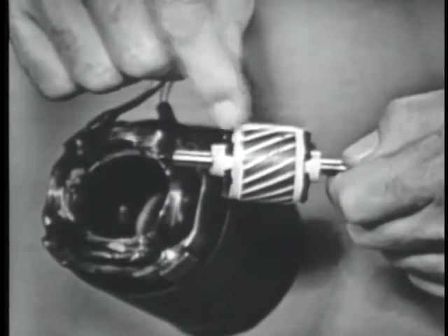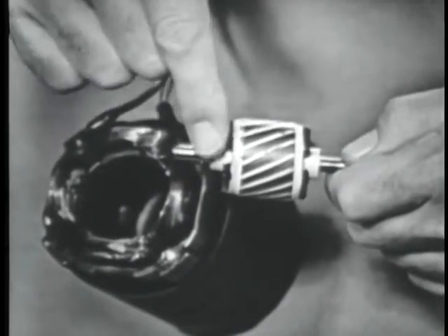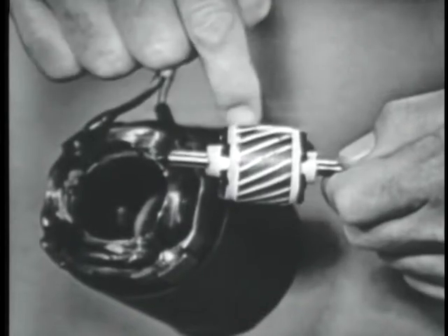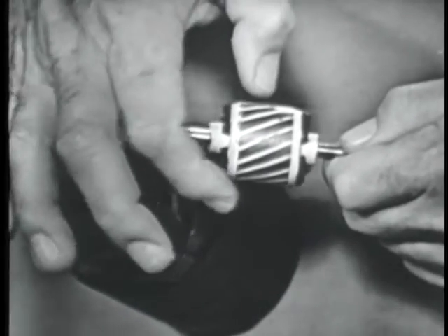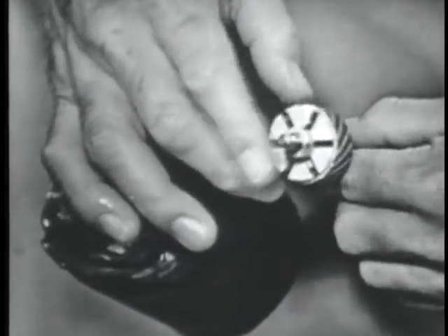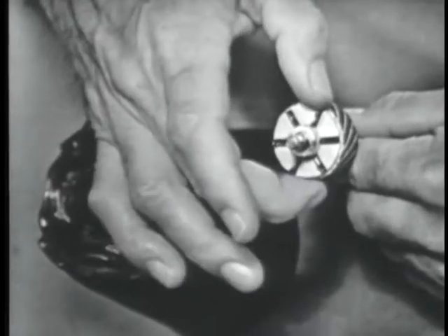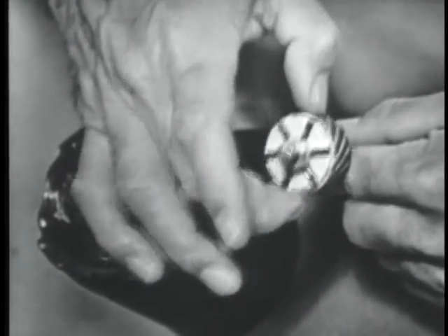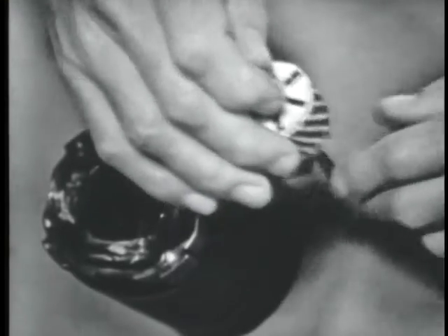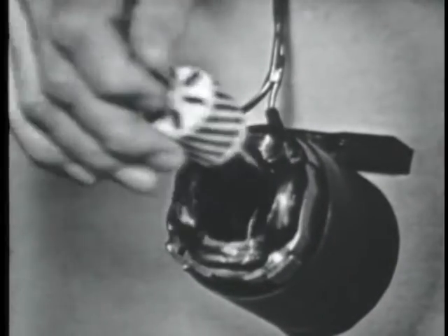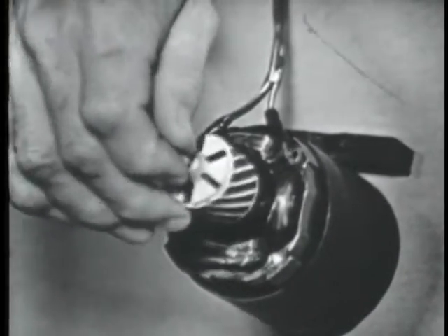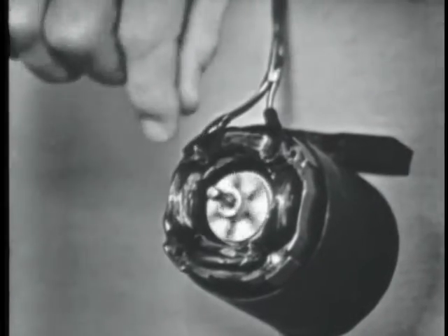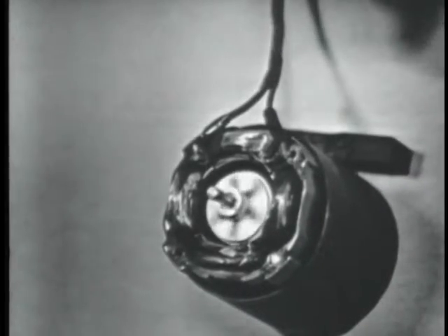Now, as the rotating field goes around this rotor, current is caused to flow in the rotor, which sets up a magnetic field, and the rotor develops a north and a south pole. Now, once we magnetize the rotor, it has got to follow the rotating magnetic field, as you've already seen, just like that. The rotor follows the rotating magnetic field as soon as it becomes an electromagnet.